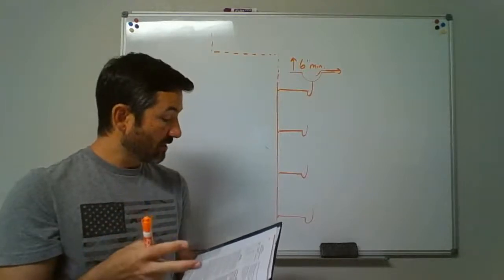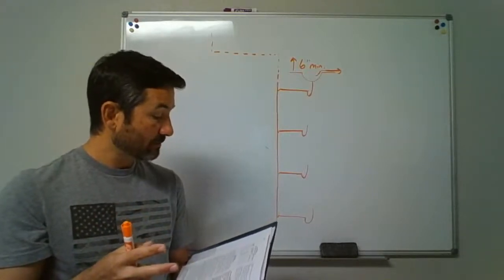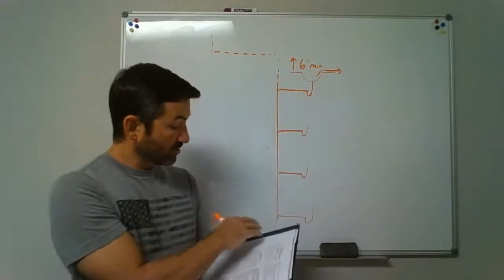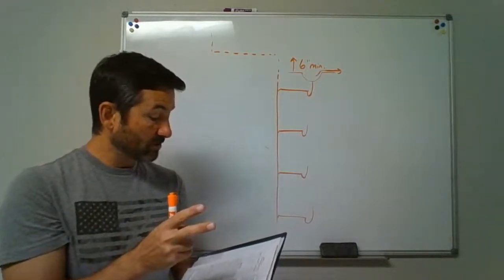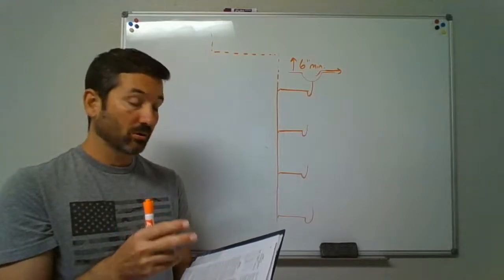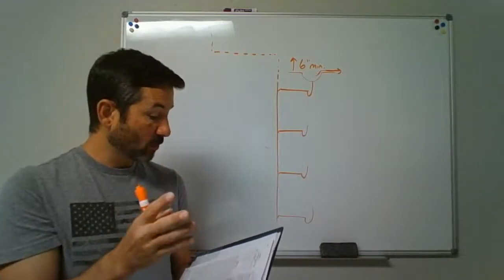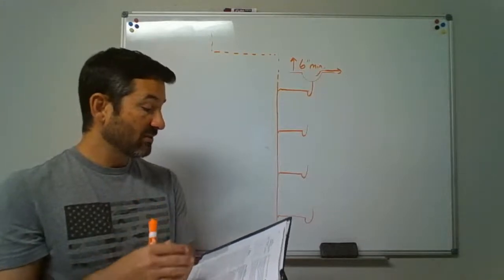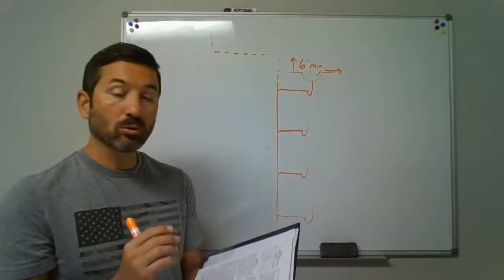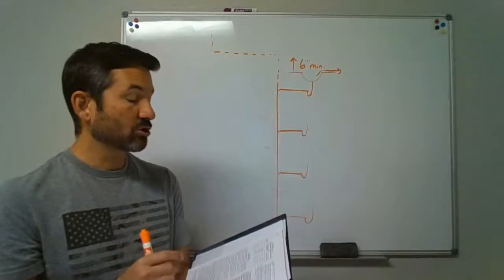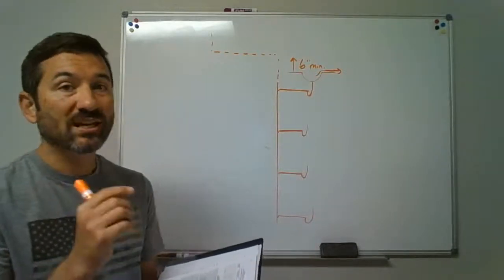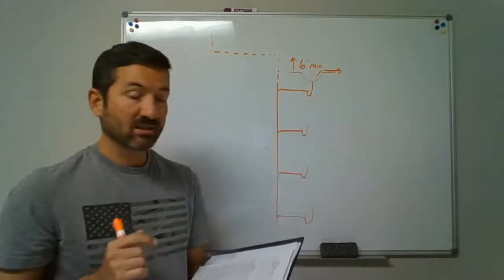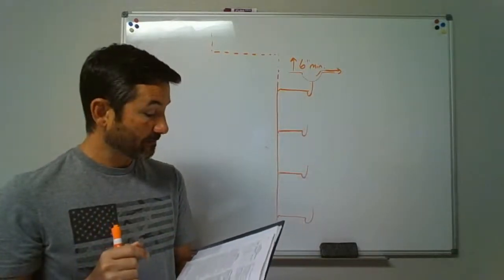But if you jump that up to a 2-inch stack size, the discharge from one branch interval could be 2 DFUs, but with a total tied into the stack of 4. When you jump up to 2.5, 3, 4, it becomes no limit to the discharge into the branch interval, which is going to be one of these branches, but it does still have a total discharge for the stack.